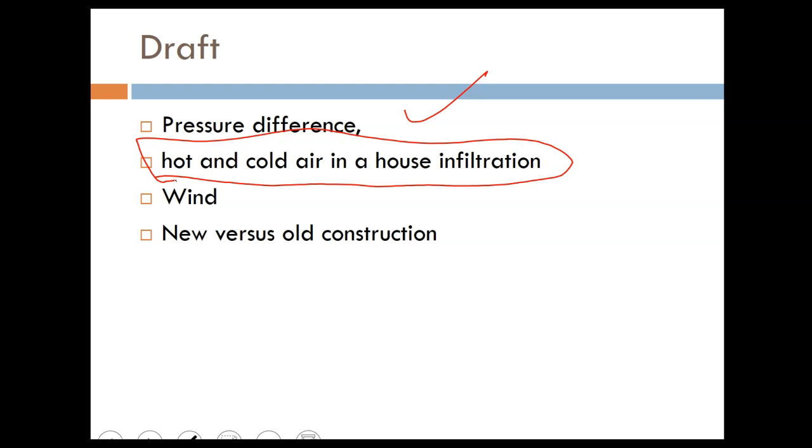So look, give it some time and watch that video and see if it makes sense to you or not. But wind does also alter the draft because it will change the pressure. What I'm trying to get at here is we want to balance the air coming inside the boiler or furnace to the air coming outside. And probably you'll see a lot of issues with furnaces and boilers where you have the hot air inside the duct system mixed with the draft air, and that's a very hazardous situation.